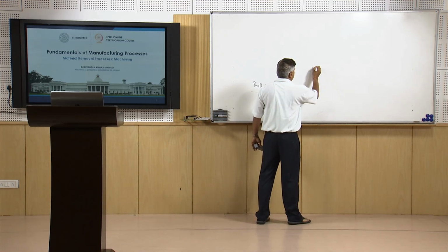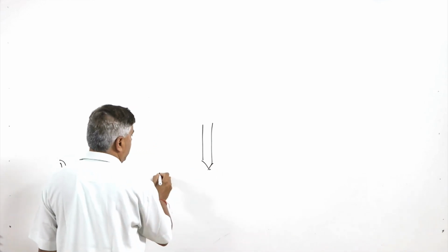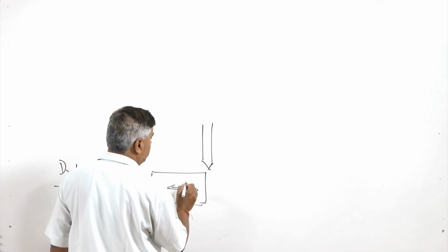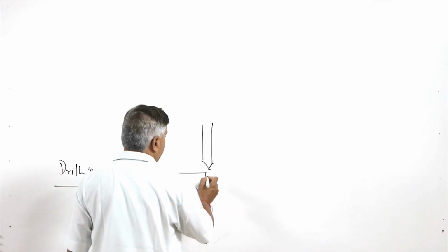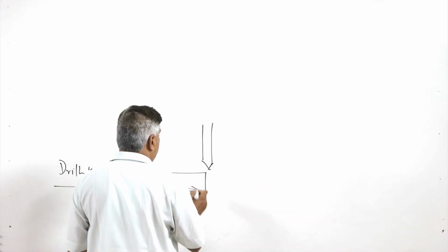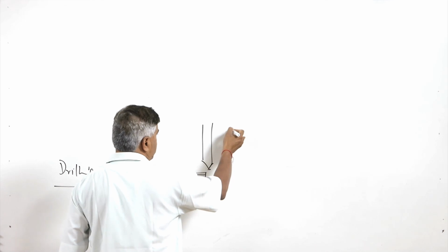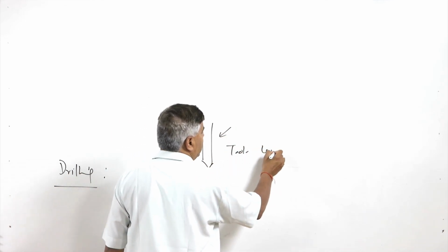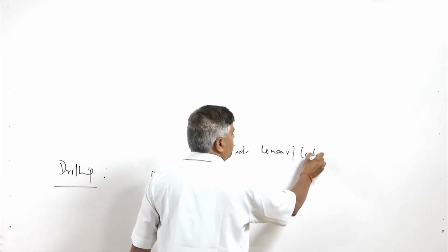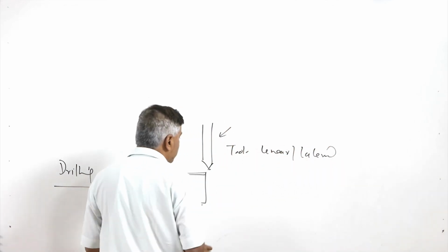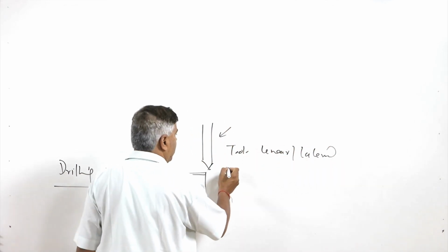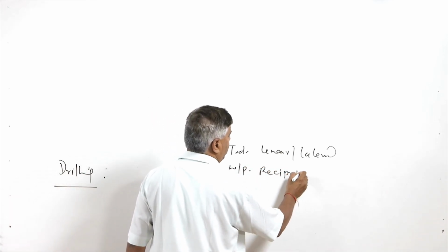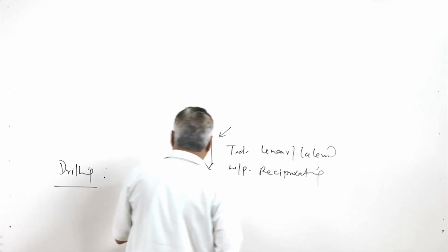The tool location is fixed and the workpiece is subjected to the reciprocating movement past the tool. When the cut is made along one line, the tool is given the lateral movement with respect to the workpiece, and the workpiece is given the reciprocating movement for producing the flat surfaces.